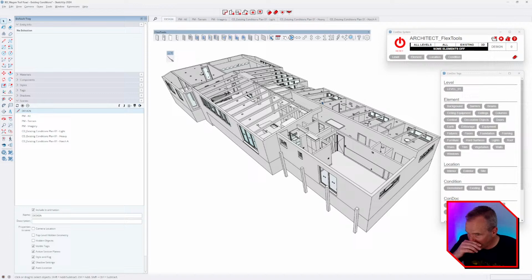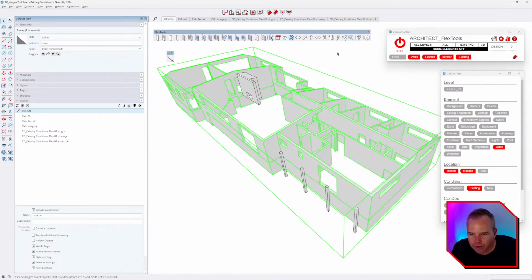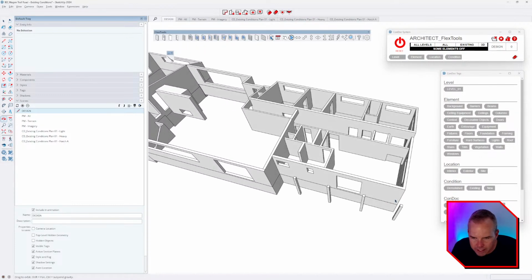This is probably the number one use for me for the Zorro tool, to separate out my interior walls from my exterior walls. When I get this scan back from Canvas, all the walls are just merged into one. So let's drill in and use that Zorro tool to slice away our interior walls and separate them from our exterior walls. To do that, I might just select a wall and hit isolate, so that we're only seeing our walls.